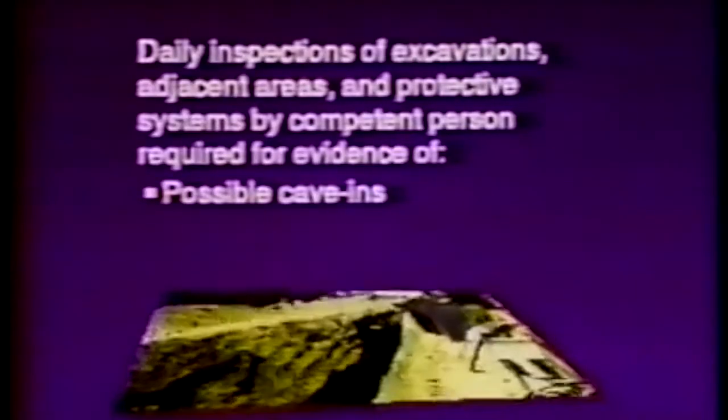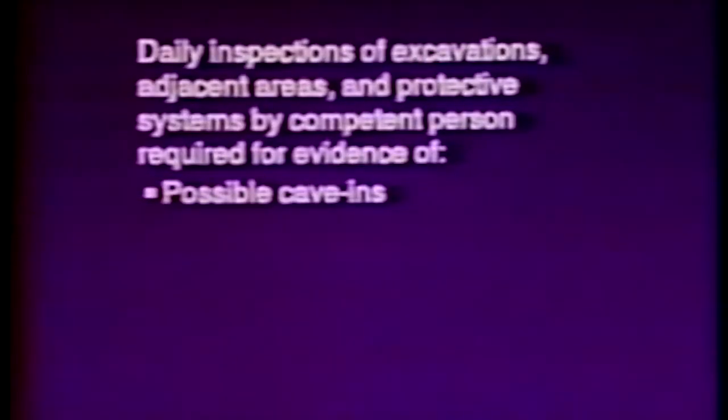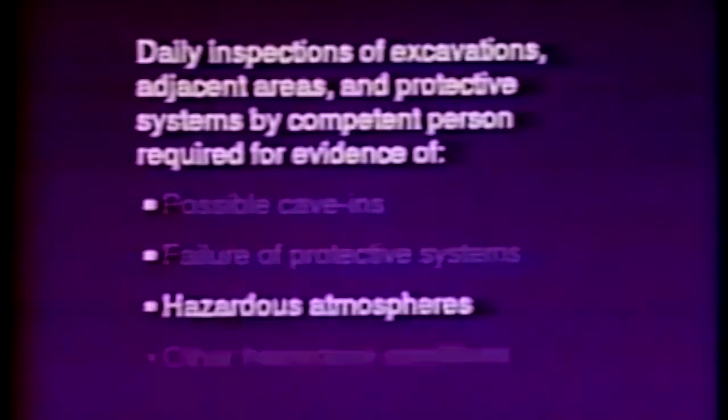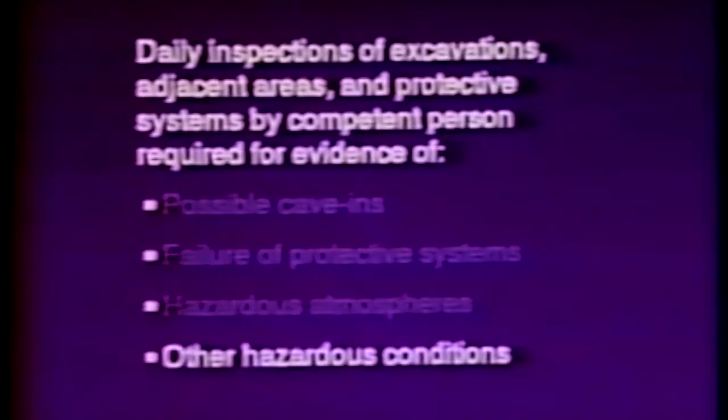Daily inspections of excavations, the adjacent areas, and protective systems must be made by a competent person for evidence of a situation that could result in possible cave-ins, failure of protective systems, hazardous atmospheres, or other hazardous conditions. Excavations subject to heavy rain runoff are to be inspected by a competent person and, as necessary, precautions instituted to protect against the hazard.